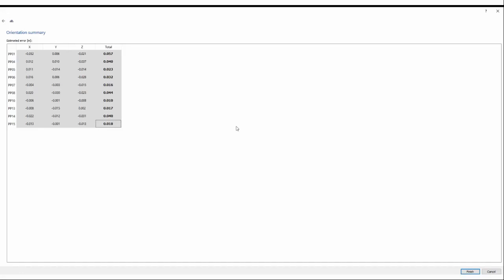But if we do position them on the ground and measure them, then we will get better results if we use the ground control points, so we don't just use them for assessing the accuracy of data. But this is something we can now expect from an RTK drone. So even without the ground control points, we can get sort of good accuracy of generated results.